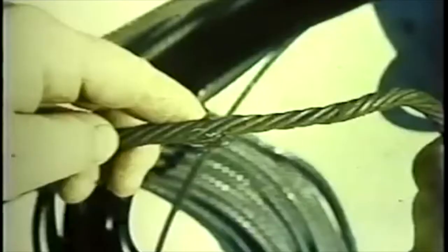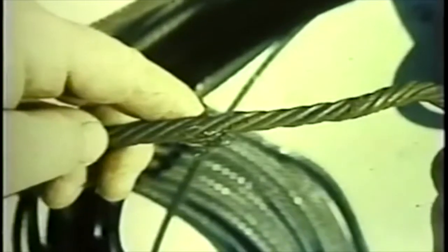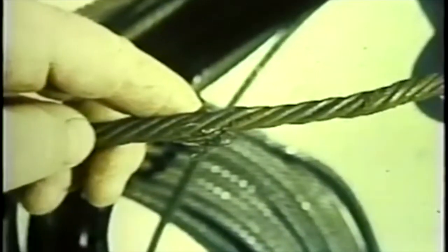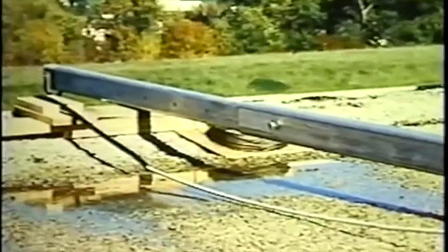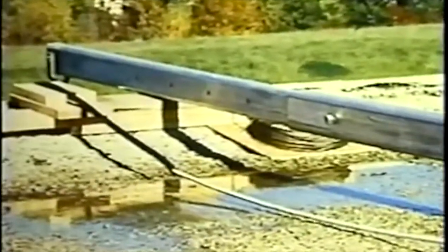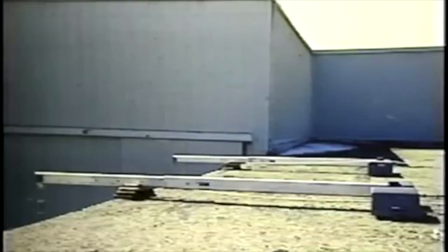All ropes, wire and fiber, hangers, platforms, and other supporting parts shall be inspected before every installation and every time it is used. 2-point suspension scaffolds must also be securely latched to the building or structure to prevent them from swaying due to winds or work activity.